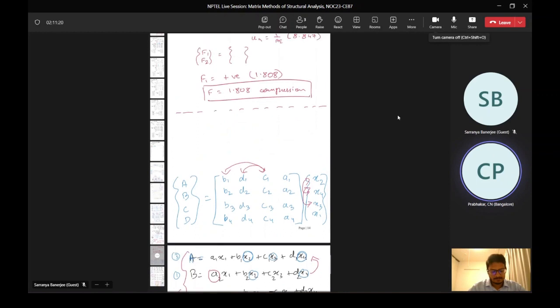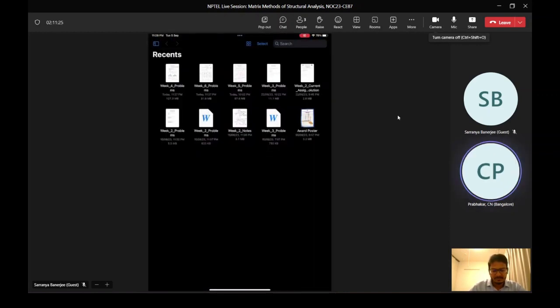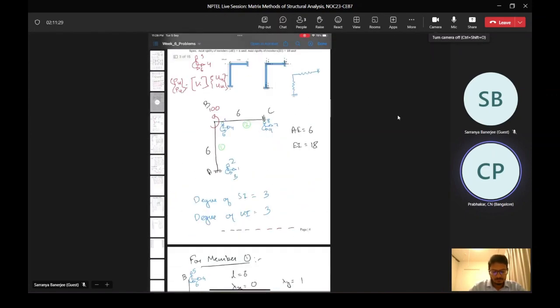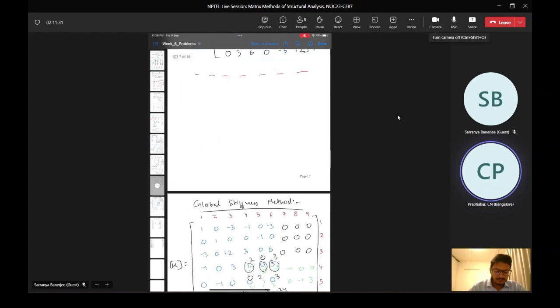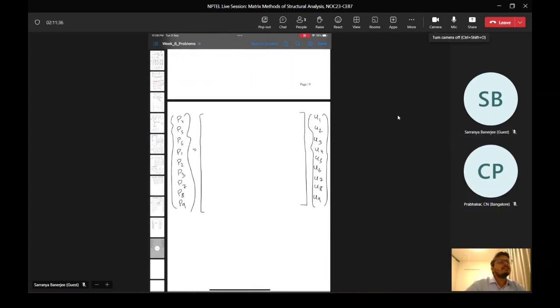Yeah, I remember that. But somehow I was thinking that we will not be changing the load vector in the first row operations, only when you change the column we have to take it up. That's what I was thinking. Okay, then fine. If you do that, then you are changing the stiffness matrix without any effect to the load and displacement vectors. But then you cannot change the stiffness matrix randomly, right? Then what is the need of assembling with so much care? Agreed, agreed, yes.